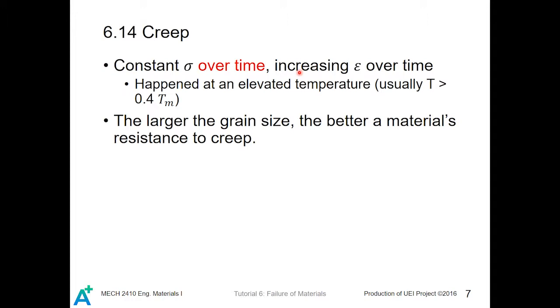For example, if you pull a bar and hold this force for a prolonged period of time, even if the force or stress applied is well below the limit, which is the yield stress for that material, the length of that material could still increase over time. And this usually happens at temperatures higher than 0.4 times the melting point of that particular material.